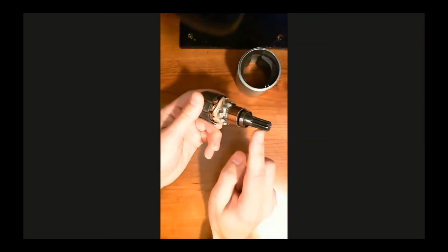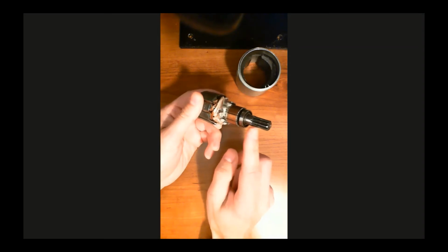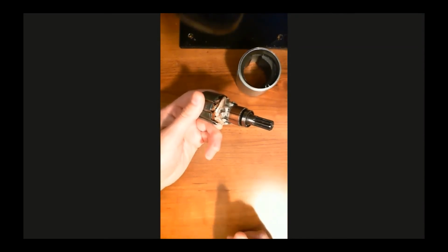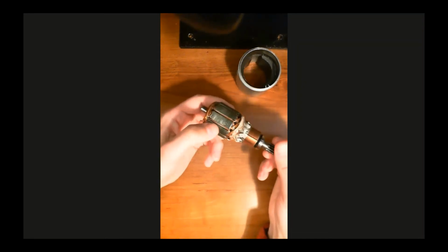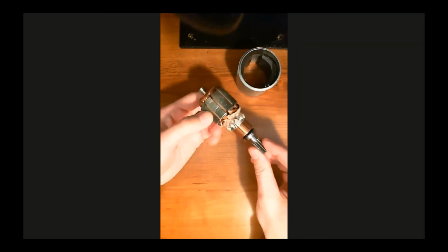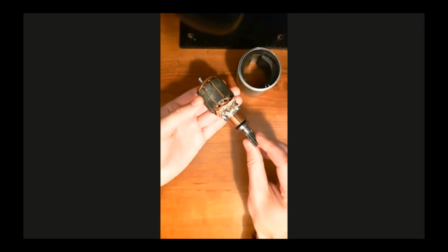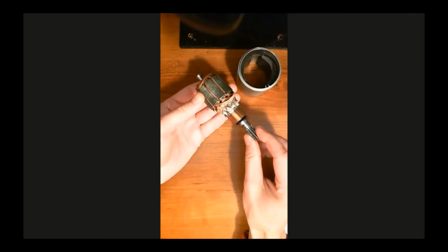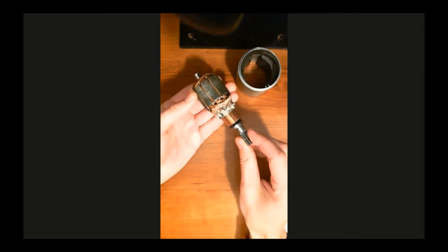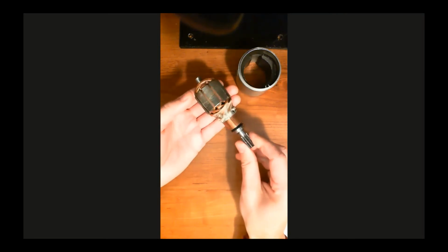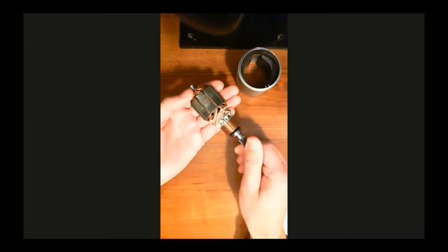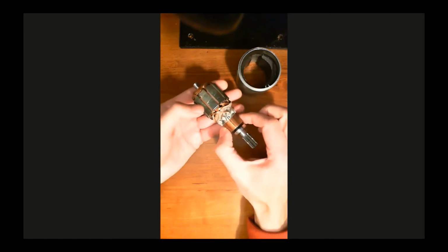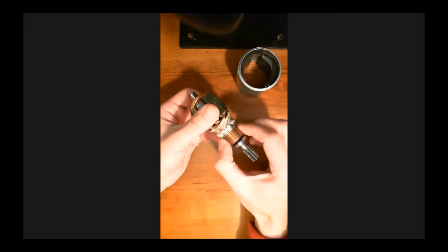So anyway, that's the output spline. That's the output driving the drill bit or whatever it is, driving the load. Alternatively, this could be a generator, in which case this would be the input. So you'd have the input from, say, a turbine, or whatever is providing the rotational input, rotating this armature, and you've got a voltage induced in the armature. Then the output is from the brushes that ride along here on the split ring commutator.